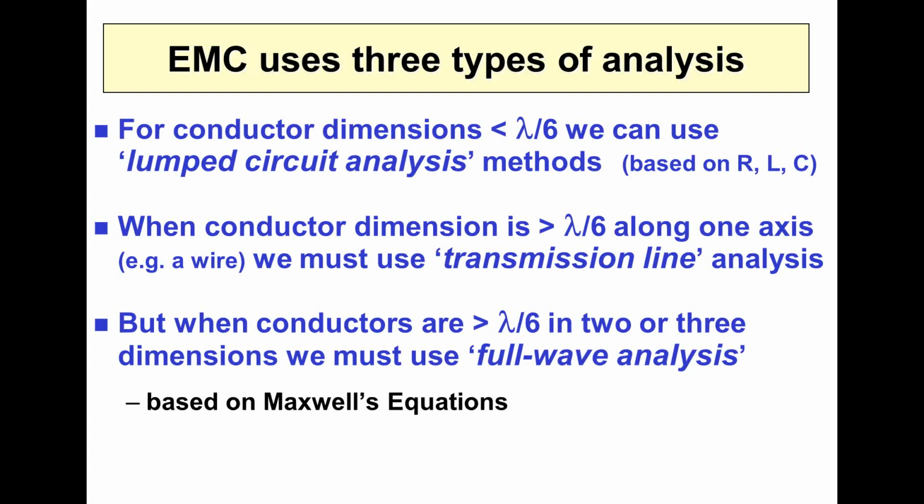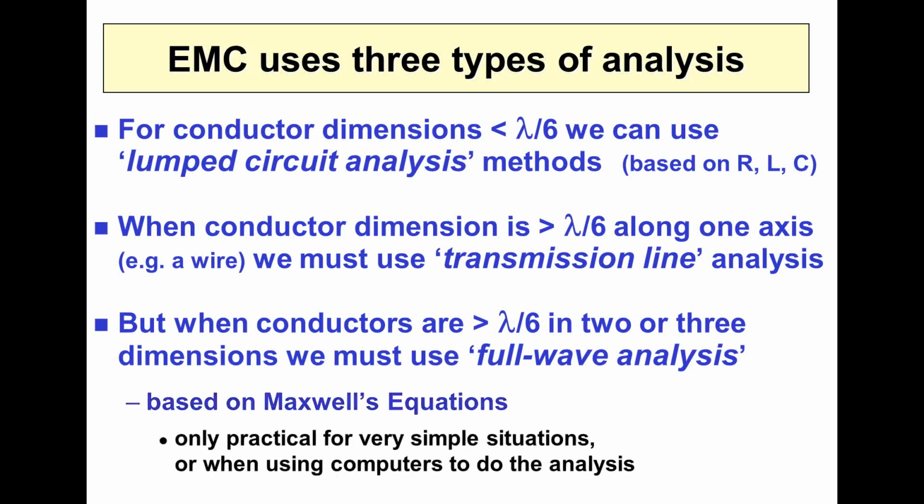Anyway, what we have now, which we didn't have 40 years ago when I met my first EMC problem, is computer simulators. And they solve Maxwell's equations on very, very small little cells, smaller than 1/10 of a wavelength, where you can simplify them. So they solve simple versions of Maxwell's equations on a little cell, and then they do the cells joining it, and the cells are joining that. And the cells might be a millimeter on the side, and eventually they can do enough calculations to simulate a 10-meter cube or something. Just imagine how many that is.